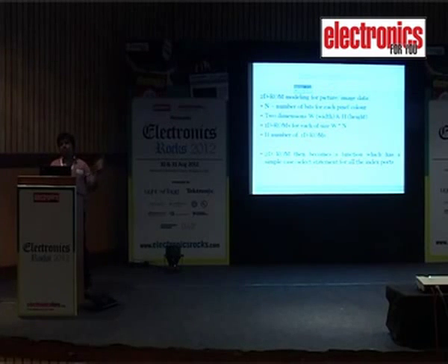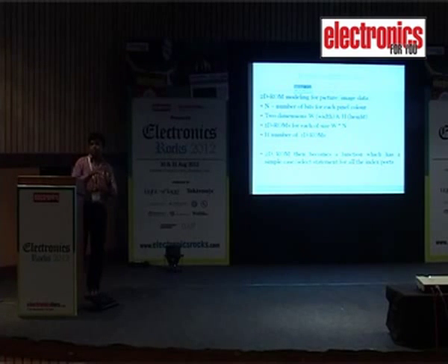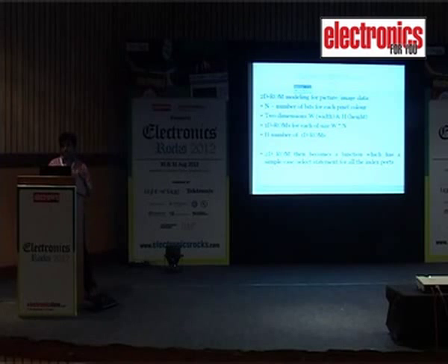The first decoder is going to decode the vertical, out of which all w or h number of ROMs are accessed, and out of them only one will be selected for a particular pixel. So when we implement a 2-dimension ROM, the output of each ROM will be commonly decoded by the address select line, and the output of that multiplexer, or that selection, is going to be the final output for each pixel.